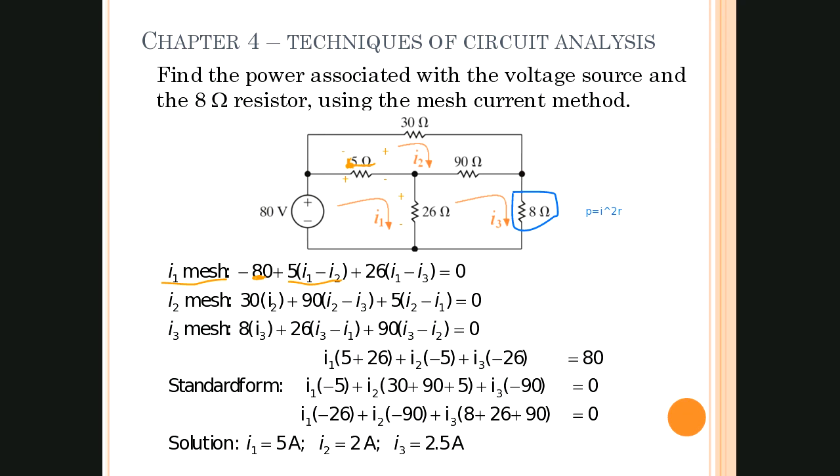The way we've drawn them, these currents are going in opposite directions. So for the mesh current through I1, it's going to be I1 minus the current opposing it, which is I2 in this case. So it's 5 ohms times I1 minus I2. We'll do an example in class before you get to your lab, because we're going to do this for the lab coming up next.